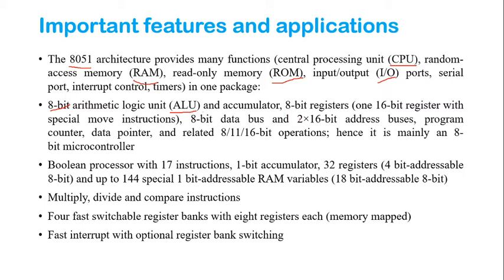It has an 8-bit architecture with an 8-bit arithmetic logic unit, that is the ALU, and an accumulator. Then an 8-bit register, one 16-bit register with special move instruction, an 8-bit data bus, and a 16-bit address bus, and a program counter, data pointer, and related 8, 11 or 16-bit operations. Hence, it is mainly an 8-bit microcontroller. These are all features of our 8051 microcontroller.